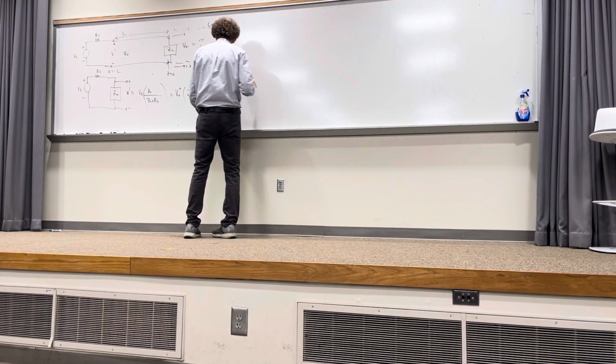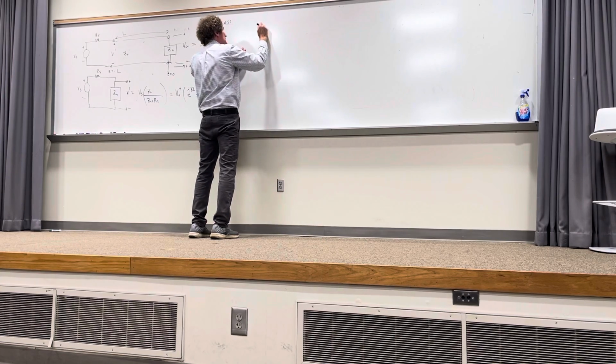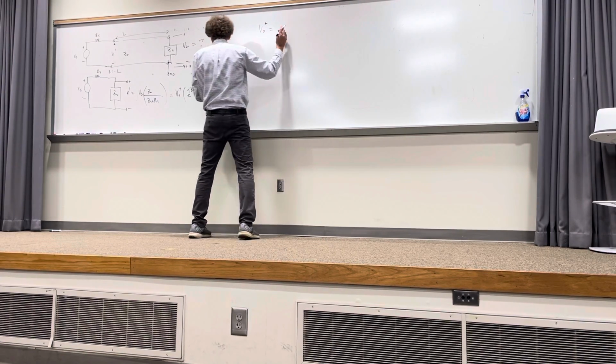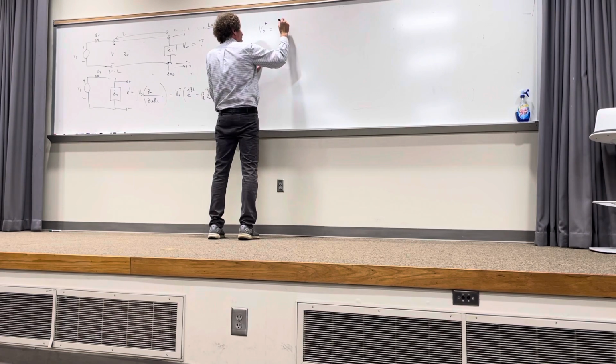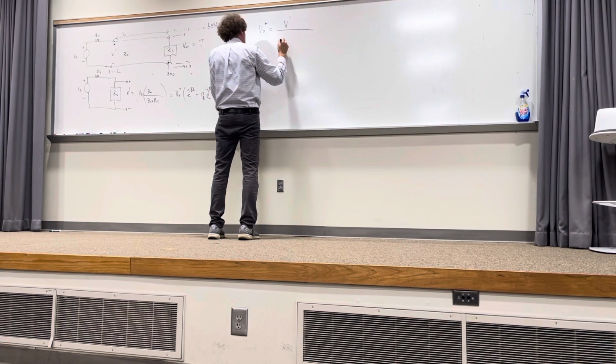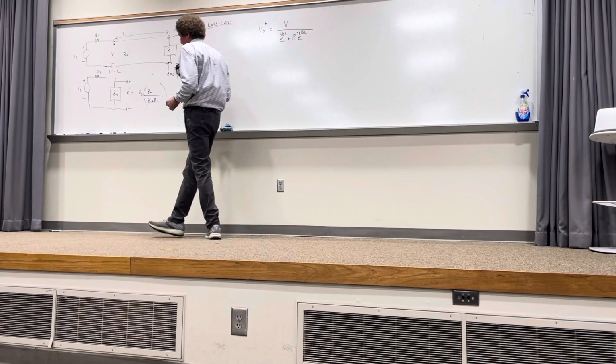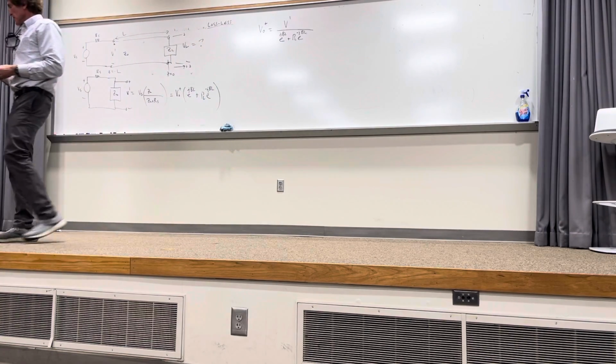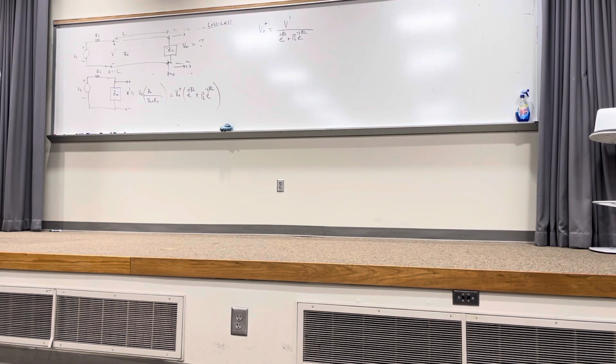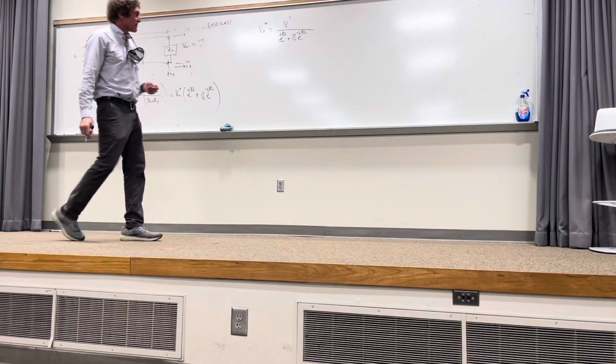All right. So if I look at this, I can say V0 plus is equal to V prime, I'm going to leave it as V prime, over E to the J beta L plus the reflection coefficient times E to the minus J beta L. And that's V0 plus. You all agree with that? And here, I'm just restating what the previous step was.